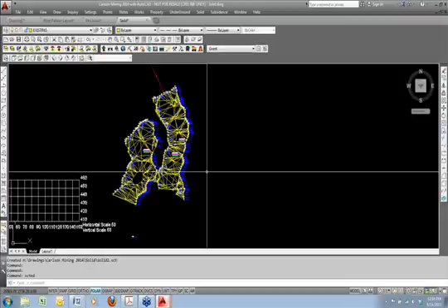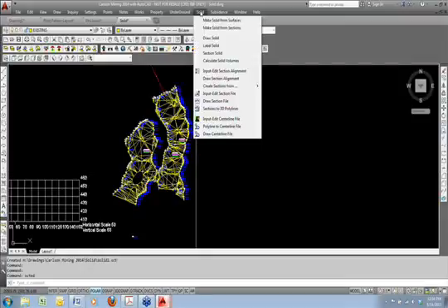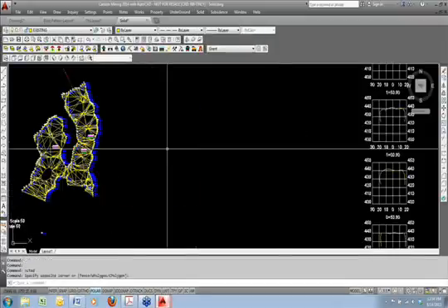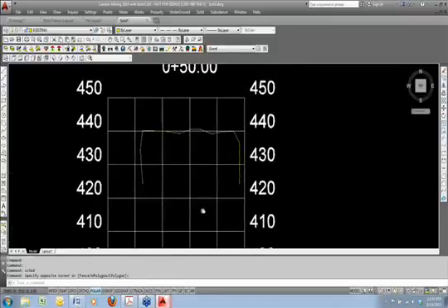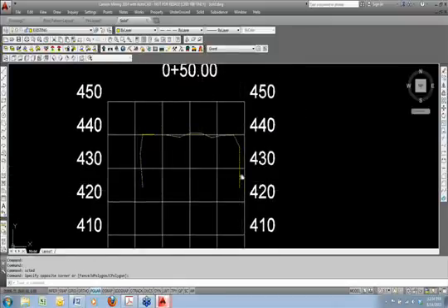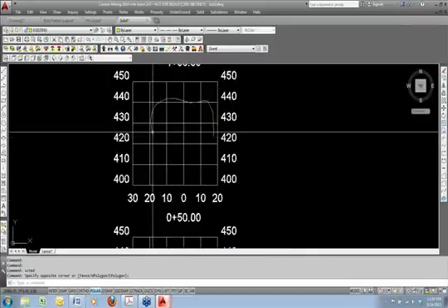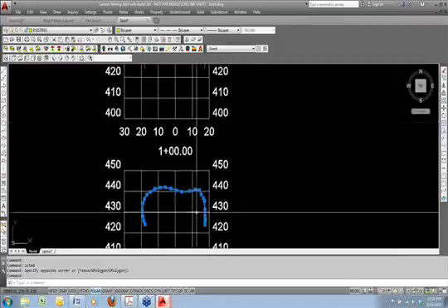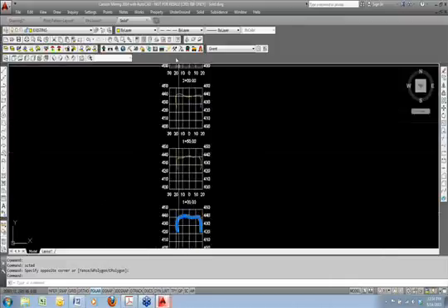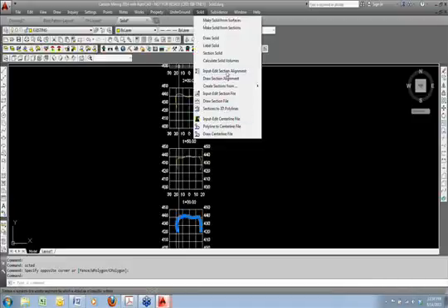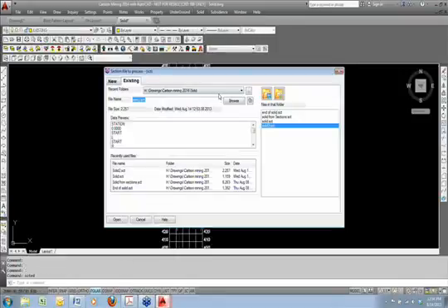All right, the next one. This one is probably going to be more common, make solid from sections. And this one looks for a survey of the actual, not the design, but the actual survey of the tunnel. And you can see I've got these cross sections every 50, and they're just 2D polylines on cross-section grids. And I made an SCT file out of those. So we'll go ahead and do that input edit section file one more time. And that would be solid from sections.